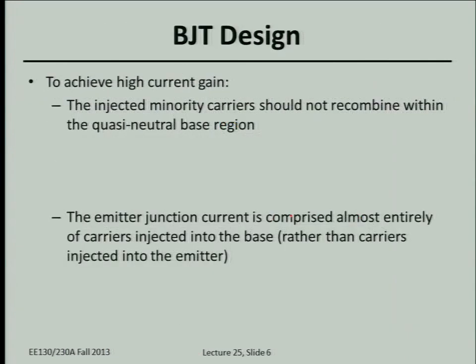Okay, so we're just going to review how to achieve high current gain. That means beta DC, which is defined to be IC over IB. Injected minority carriers should not recombine within the quasi-neutral region. So that means the width of the base, let's be specific, the width